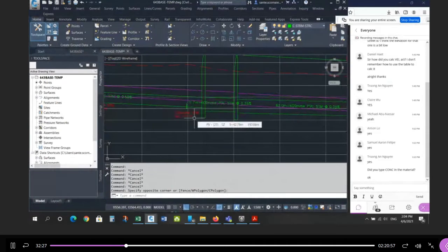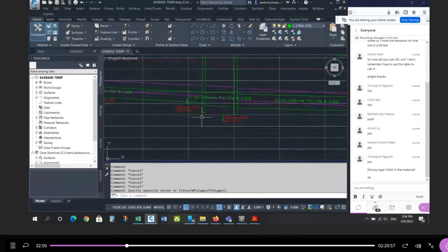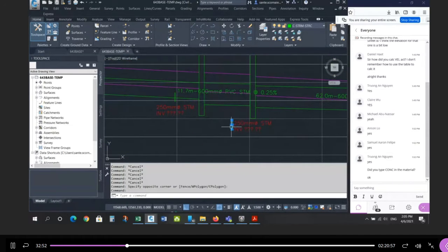Okay, it might come back that I have to make all these flat 0.25 pipes at least 675, the next size up. But I'll know after the town reviews it. So I'm just going to put it in my favor. I'll use the smaller pipe for the flat, the 600 instead of 675. Okay, so now what else can I do? What else can I do? Well, now I have no choice but to raise these.